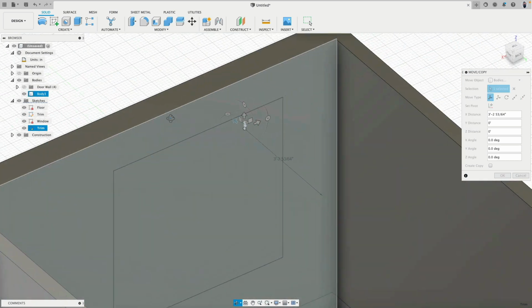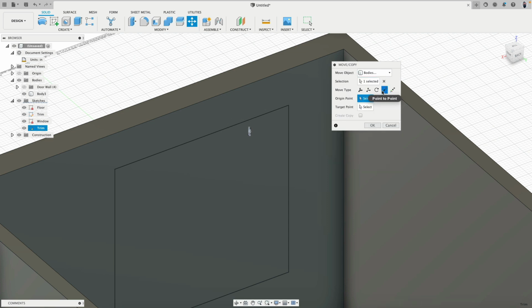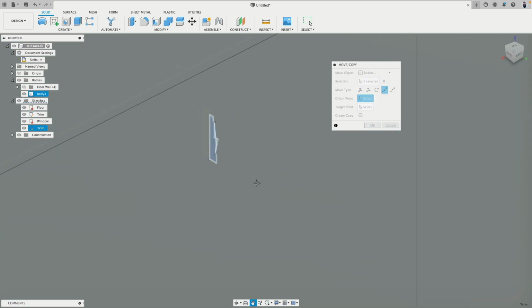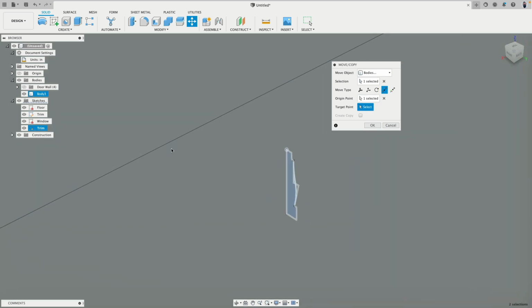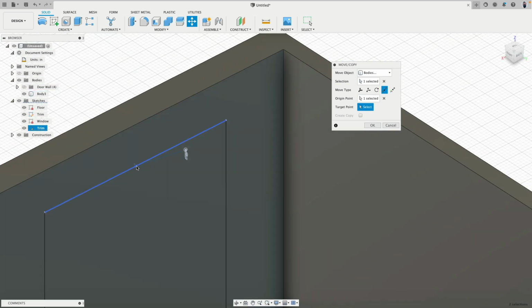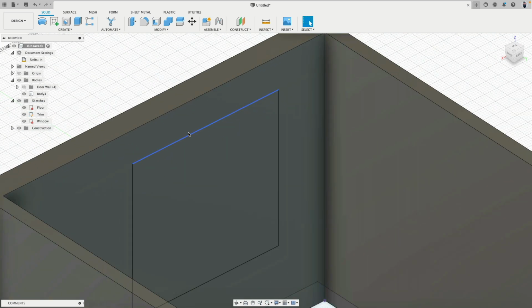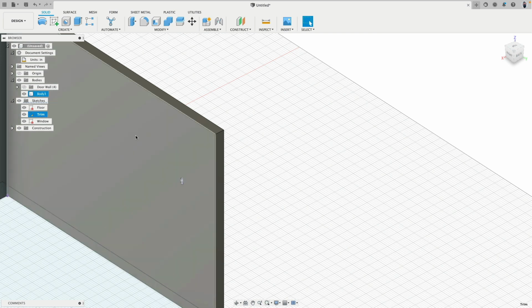No, I don't really know where this is. And here is the move command. Now we have move freely and rotate. And then we have this point to point. That's kind of like what I want. So the sketch is selected and I would like this corner point to align with this midpoint. Okay, there. You see? Let me do this one more time. So I select the trim sketch in the object browser, copy and paste.